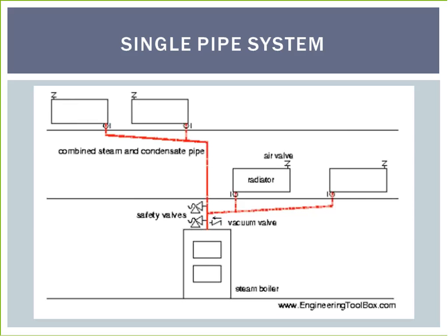In the oldest modern hydronic heating technology, a single pipe steam system delivers steam to radiators where the steam gives up its heat and is condensed back to water. The radiators and steam supply pipes are pitched so that gravity eventually takes this condensate back down to the steam supply piping to the boiler, where it can once again be turned into steam and returned to the radiators.